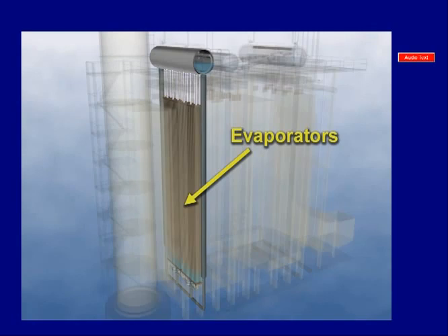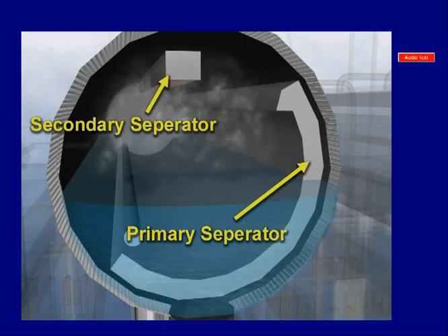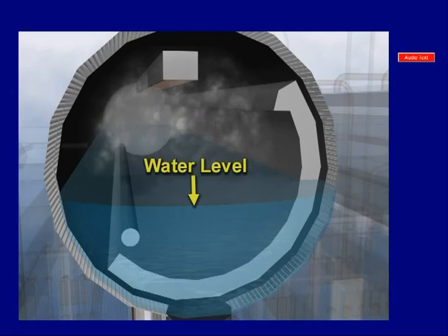As this steam-water mixture enters one of the 3 drums, it first passes through the primary steam separator, where water and steam are separated. Before leaving a drum, the steam passes through the secondary separator and leaves the drum through a saturated steam line. The LP, IP, and HP drums are designed to contain the expansion or swell of their individual evaporators, which occurs during startup due to the expansion of water that is being heated.